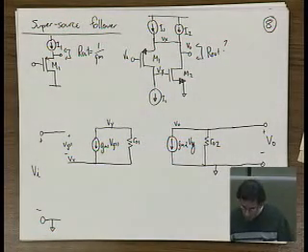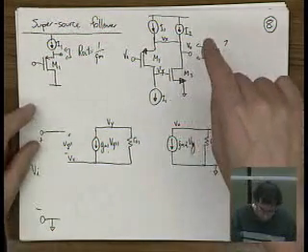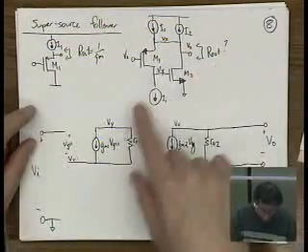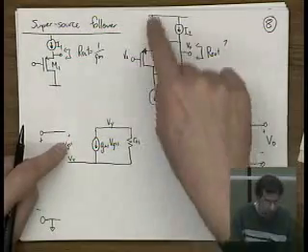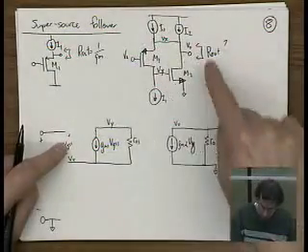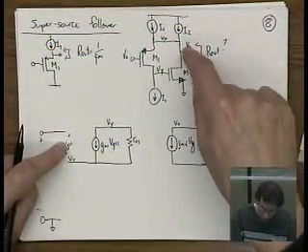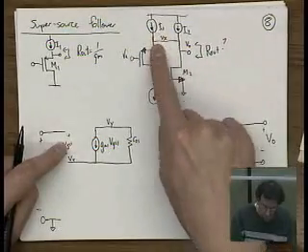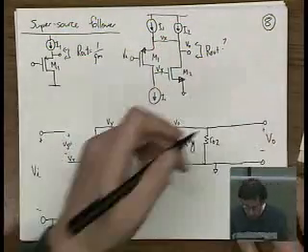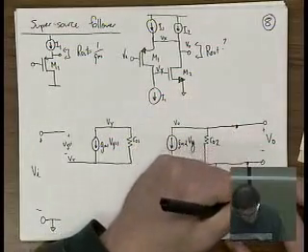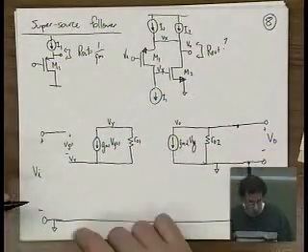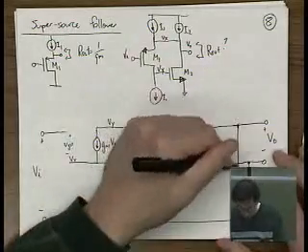What I'm actually doing is, if we look here, I've calculated Vy. It's based on VGS1, GM, R out, and these current sources go away, and then gain that up to get V out. What we can see here is that V out is equal to Vx, right? So we're taking V out, the negative terminal of V out goes to ground because these are all a common ground node, and we're doing this.